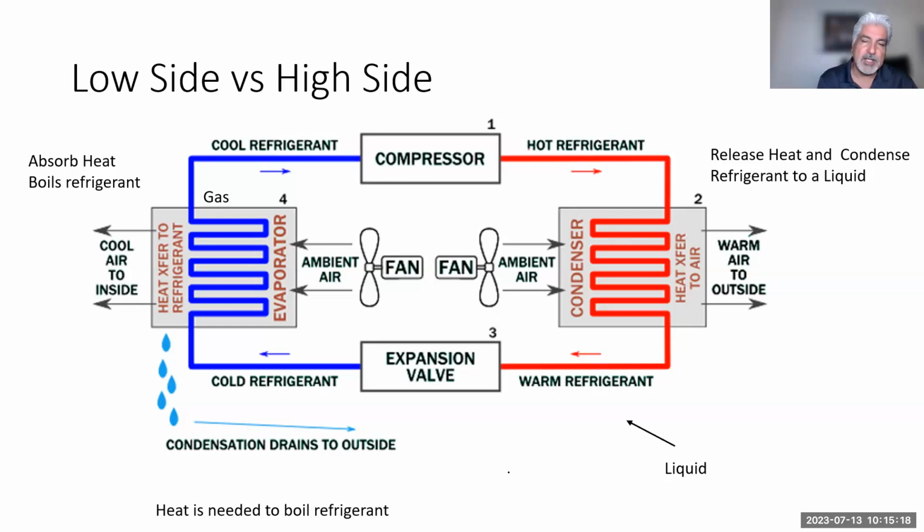Some models use a relay, some models use a module. I know, I get it. But in this case, or a blower motor resistor too as well, again, you've got to make sure it's getting full voltage. So if the voltage on the truck as it's running is 13.4, what should I see at the blower motor? Ideally 13.4. Yes, I know there is a quarter of a volt variance. You have a leeway, but if it's like 13.4 at the batteries and you're getting no more than 12.2 at the blower motor, then you've got a problem in the circuitry.